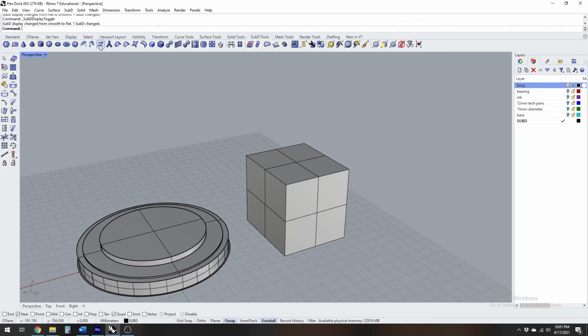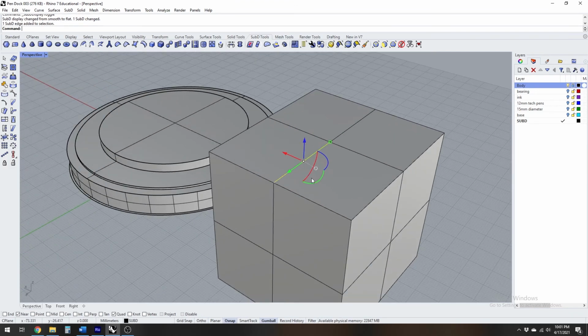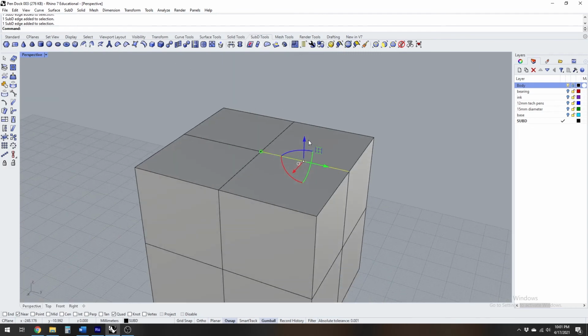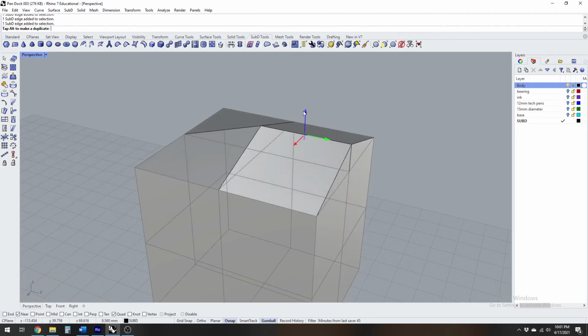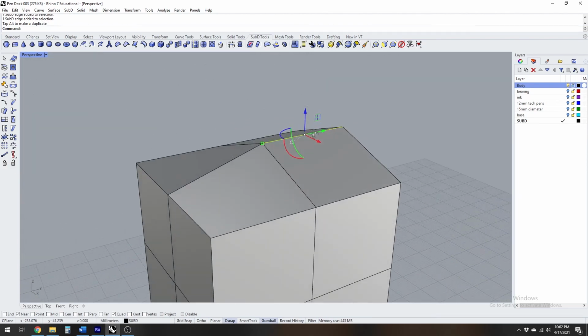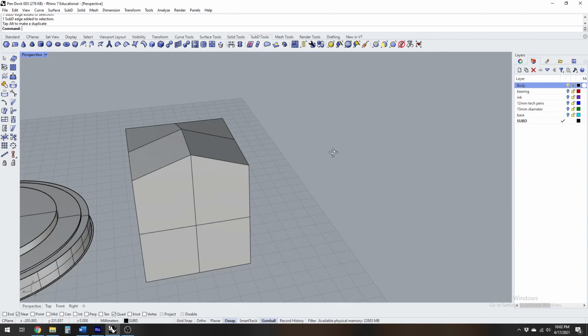You can see we have lots of different tools for changing where our edges are, adding creases, removing creases. We can loft and rail and create ellipses and spheres, cylinders, truncated cones, all the things that we have in NURBS. What I'm doing now is selecting the actual vertices. So you can select edges and vertices and then live transform them, and the object will deform all of its surrounding geometry to accommodate.